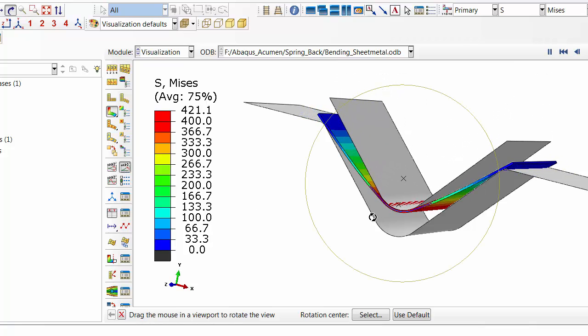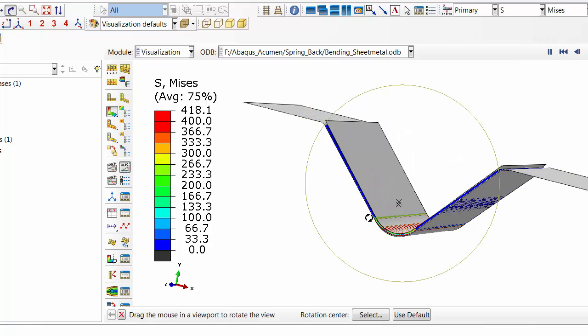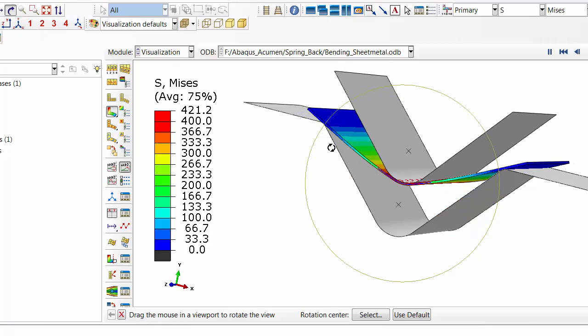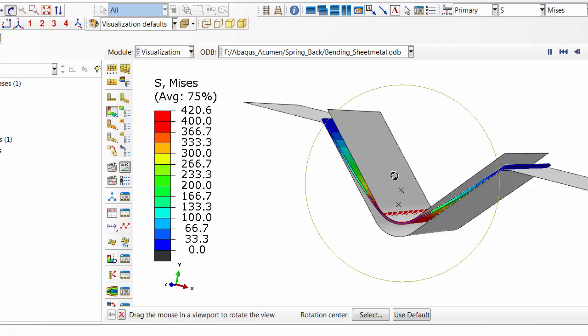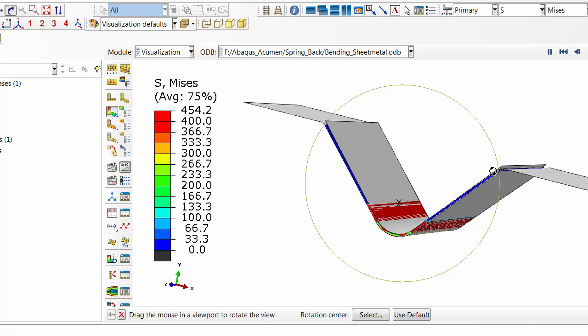Right now it looks okay, the plasticity zone has developed. There are some areas in the elastic region which may get a spring back, but a spring back of 2 to 4% is okay. Once you take this piece out and keep it open, it may just spring back. That is a different topic, we can touch on spring back sometime.